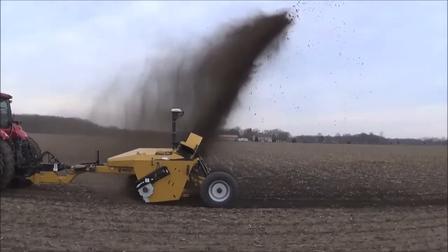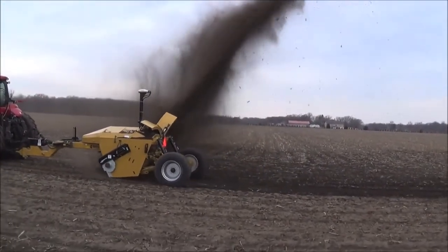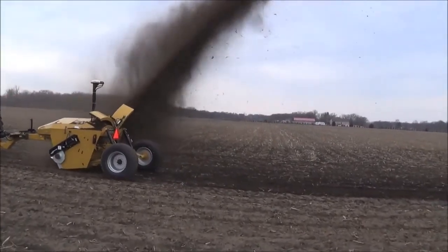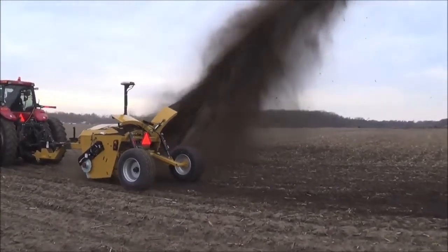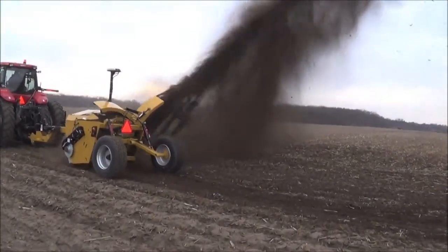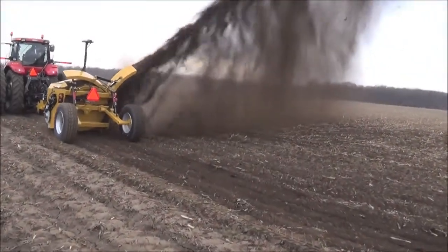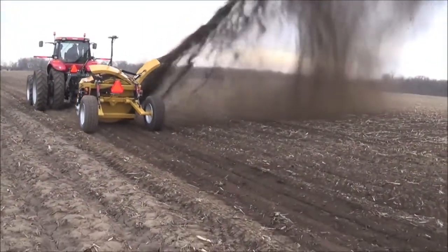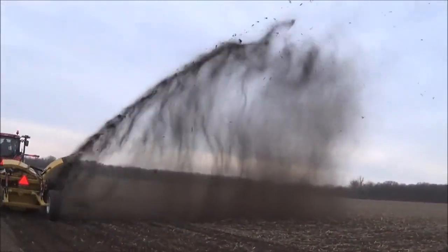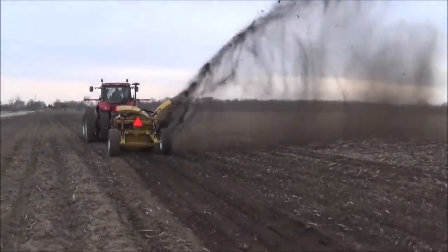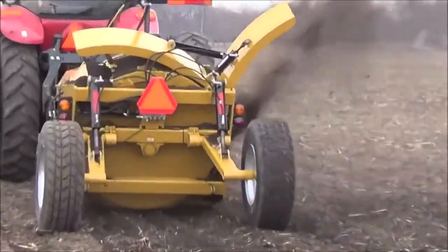So okay, how is surface drainage or waterways conducted on what is considered flat country? It is either via the traditional dirt pan, dozer, and/or grader. But what some have done in other areas is use a dirt blowing machine. These machines can do the job in about half the time. You don't have to find places to put removed dirt, and the compaction from the use of the other previously mentioned equipment is non-existent.